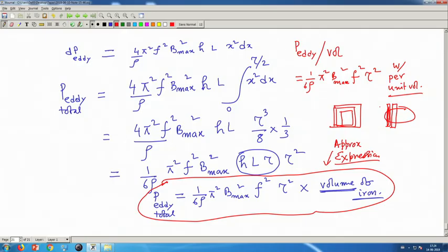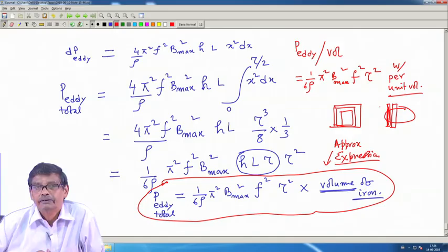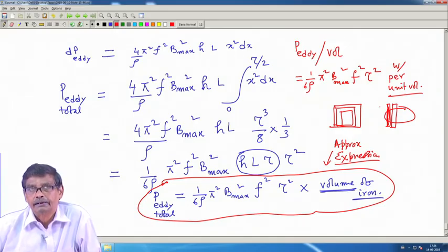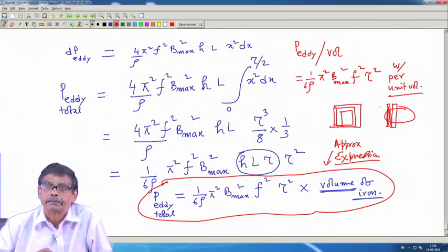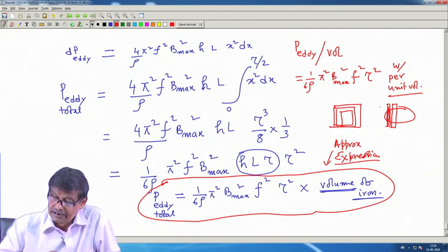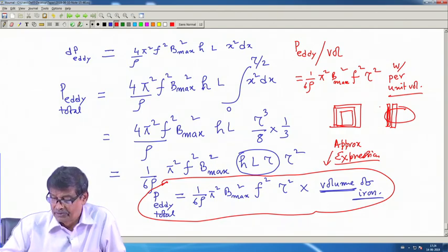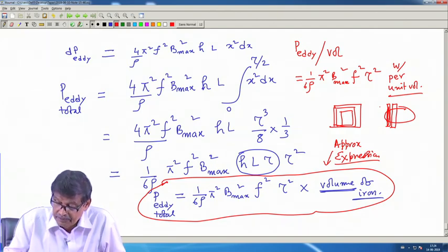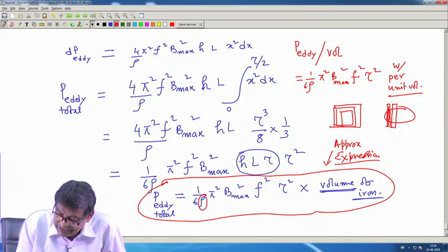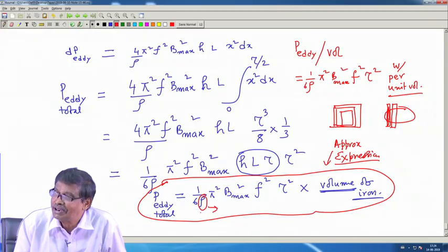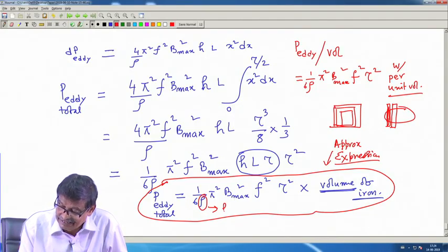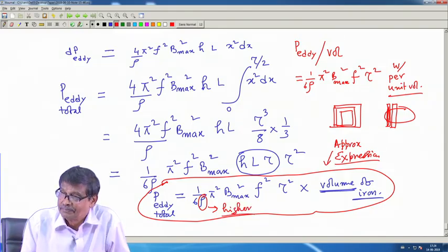Therefore, we know that. So, how to reduce then eddy current loss? Because it is a wasteful energy. Transformer will be on 24 hours, okay? And eddy losses will always take place. If that be the case, you try to use such a material whose resistivity is higher. Rho should be made higher, at least this is apparent.